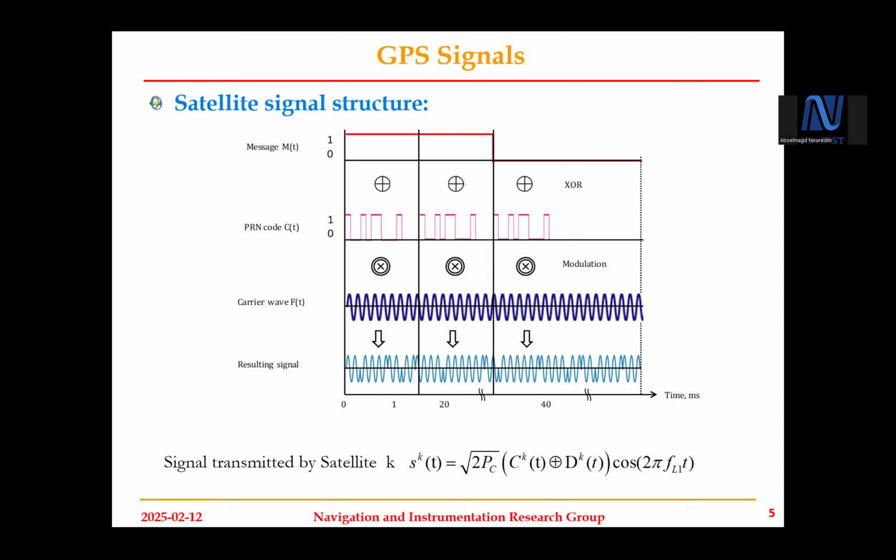No change will happen. But if the resultant bit is 1, then the signal phase is shifted by 180 degrees. This is not very accurately reflecting, but I believe you understand. If the signal phase was moving up like this, it will move down instead. That means we shift the signal in phase by 180 degrees, or pi if you wish.